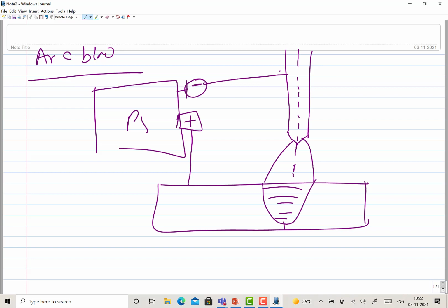When you have things in the vertical position, the axis of the electrode is almost 90 degrees. But usually, the axis of the electrode may vary, say 45 to 60 degrees, when we are performing manual metal arc welding. This may be true for TIG welding as well. So what's happening when the electrode moves towards the sides, say this is the arc location? Around the arc you have certain things, like the flow of current from the negative terminal to the electrode, and the current is flowing like this.